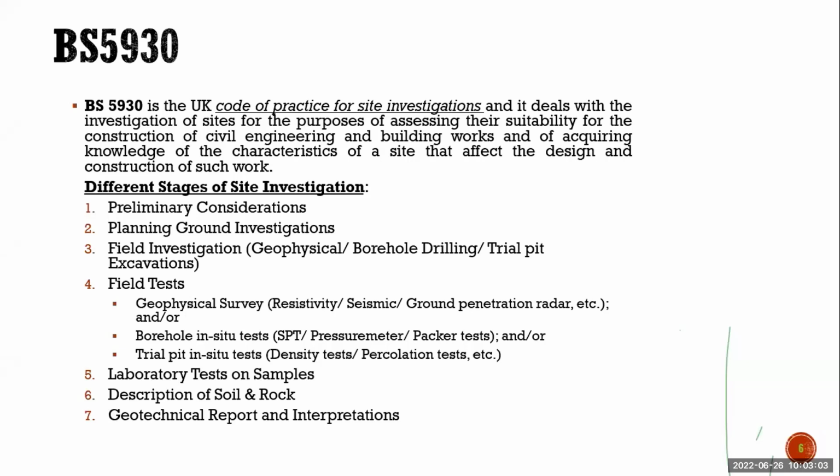They will do the cavity detection through some specific geophysical methods. Then once they get the result, they will know these are the places where they are getting the anomaly. So at those places specifically, they will perform borehole drilling to reconfirm whether these particular findings match the interpretations or not.